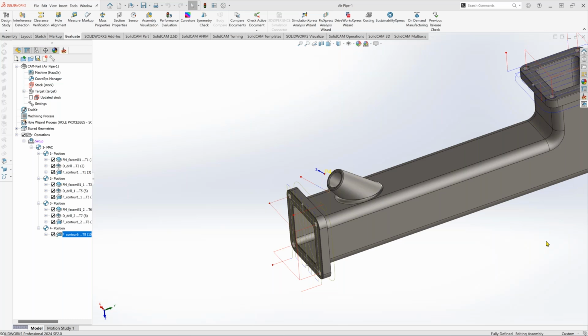It's very dependent. If you define it as it's written in your book, for example, if you work on a Mazak machine, you will define it as a single angle. If you work on a Fanuc head machine, it will always be 3-axis or Euler angle. You have to know exactly what the rules on the machine are for how to define the tilt plane.